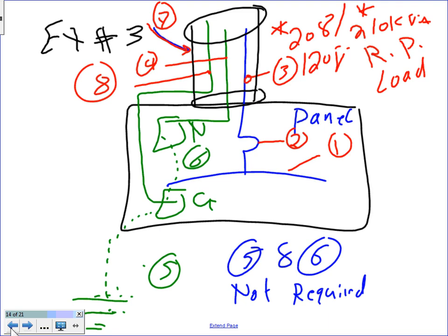Yesterday, a lot of you asked me what size transformer do I need, and what did I tell you to do? I said take the amps of your panel, multiply by the voltage, multiply by 1.73, go to Home Depot or a supplier, and find yourself a transformer that can get you this kVA or higher. That's what we're going to be doing. But I do have 3 examples, really good ones, that go through the whole calculation. Match a transformer to a panel.